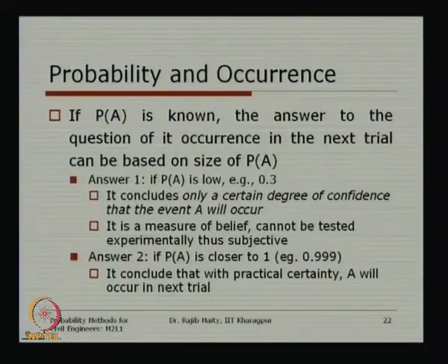And I say that this probability is, say, 0.05. Now the question is, in the next event of the rainfall, what is the chance, what is the occurrence that that particular rainfall value will really be exceeded? So what does this 0.05, what does this number actually give you to infer? This is the topic of this particular slide.